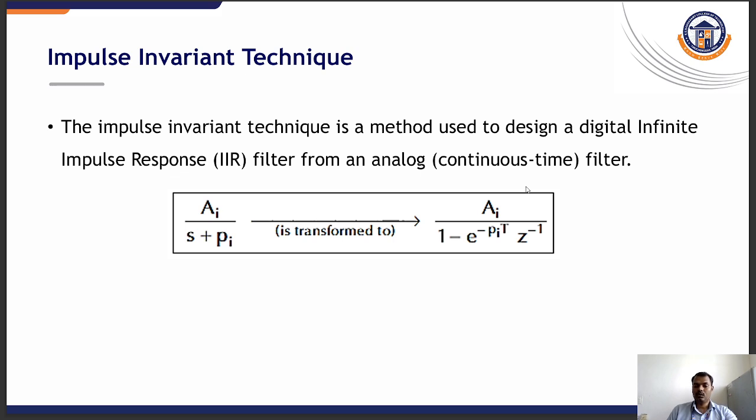It provides a more robust solution by using a different mapping from the S plane to the Z plane. The transformation is based on the substitution of the s value. This solves aliasing because the transformation is a conformal mapping that maps the entire imaginary axis of the S plane onto the unit circle of the Z plane. Unlike the impulse invariant method, which has a many to one mapping, the bilinear transform's mapping is one to one. This prevents aliasing because the entire infinite analog frequency range is compressed into the finite digital frequency range, that is minus pi to plus pi.